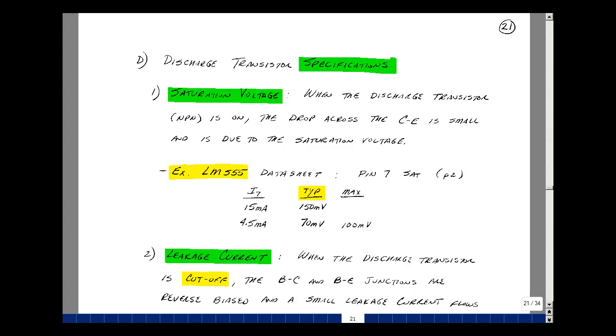Again, that's the voltage between the collector and emitter when we saturate. This was actually on page 2 of that datasheet. And typically it was listed as 150 millivolts. If you recall from 302, we were using 0.2 for our typical value, or 200 millivolts.